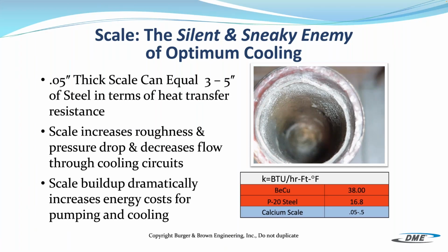Other inhibitors are blockage, so any scaling, any blocks, any rust, anything that goes into the circuit, and then also the flow rate. So if we're not getting optimal flow and optimal water characteristics, then that's going to be a big inhibitor to optimal cooling.